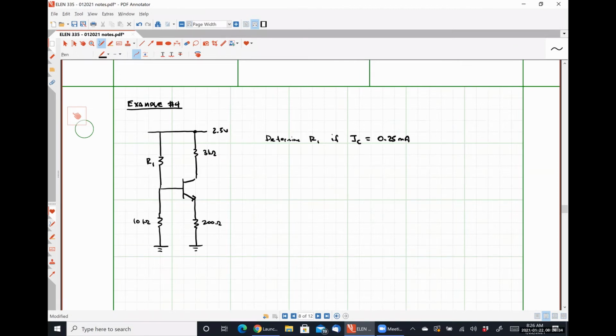So if we want to design a particular amplifier, we typically design for what that is on the biasing side. That means we are designing for what specific value of IC we want to have as our operating point condition. So we're figuring out what resistors will make that happen here.